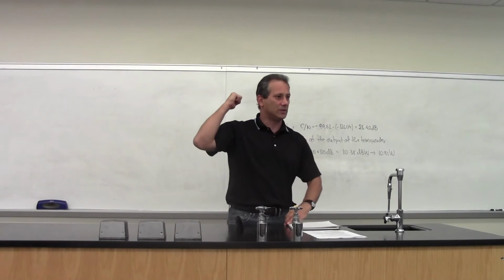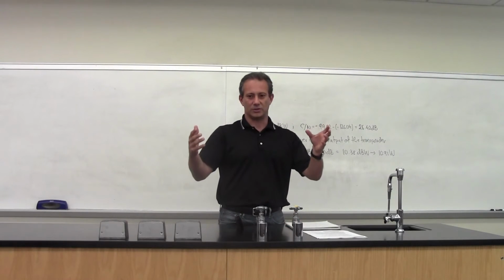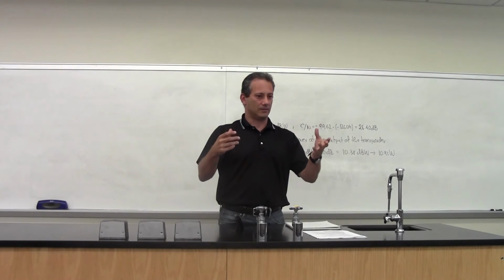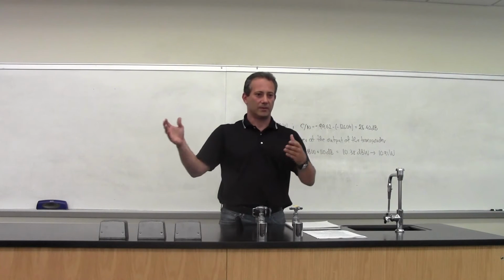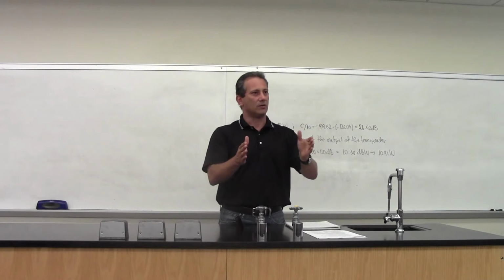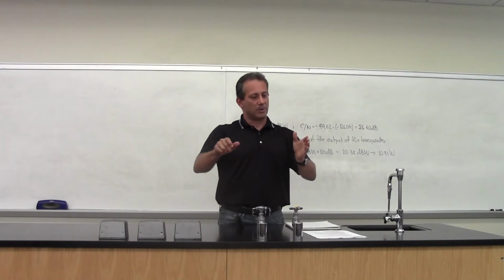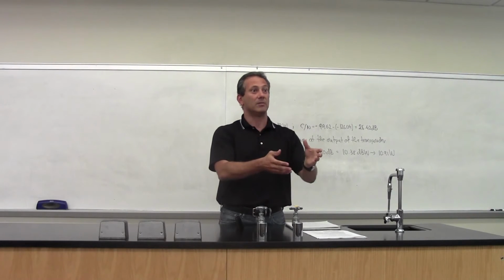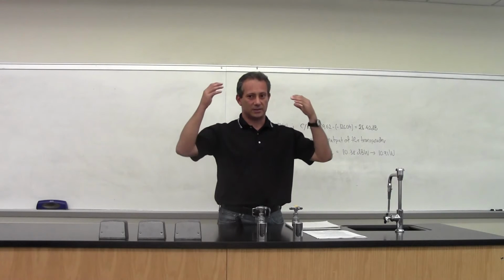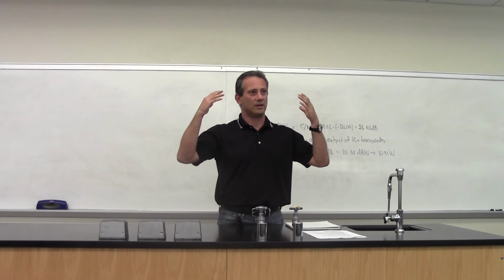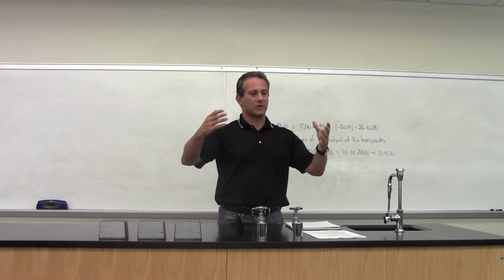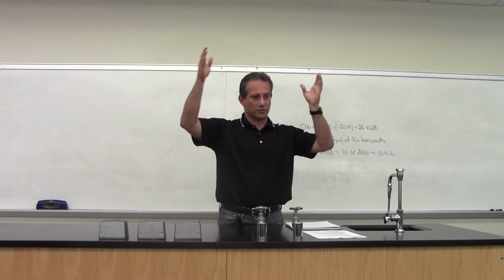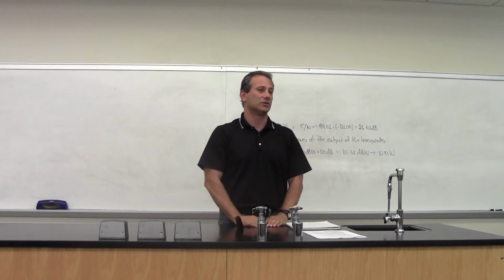You can go through the detailed analysis, but I know a lot of you are musicians, so you know that if you play any instrument through an amplifier at low volume, it comes out clean. But start cranking the volume, and eventually you overdrive the amplifier. What that does is the signal becomes noisy. Part of that noise is outside of the audio range, but part of that noise falls right in the range where your signal is, and your signal is distorted.